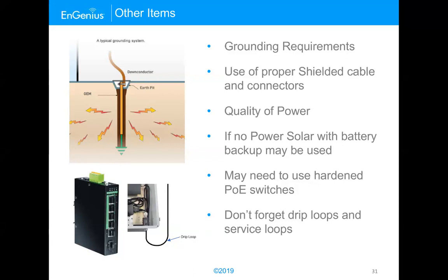Now, it's not just as easy as just grabbing a solar panel from Fry's and installing it. You've got to take some planning and consideration there. What's the size of the panel, the quality of the panel? That all has got to go through some mathematical equations to determine what size you need, what part of the earth you're going to be deployed in, how much sun you're going to be getting. Battery backups, how big of battery backups you're going to need, how much equipment is going to be used, in amp hours.